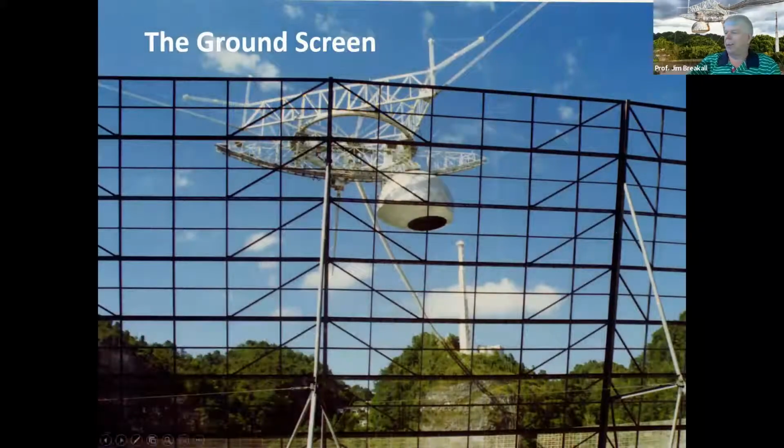Here's this big reflecting screen. This is about 60 feet high, or about 20 meters. And this went around the whole dish. This was basically to keep out interference, and to shield the ground. The ground is at a very warm temperature, but the antenna is at a very cold temperature called the sky noise that it sees. And so you don't want to have the antennas looking at the ground. And temperature is very important because that allows you to see much weaker signals.